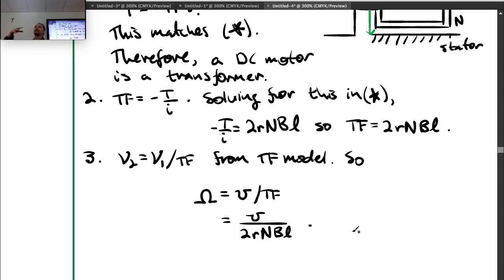Maybe you're trying to lift something using a motor and you can't lift it. You're just trying as much as you can. If you've got constant power, then as your omega goes down, your voltage goes down. If you're still delivering that power, you've got to increase your current more and more, and that's what happens. You start pulling more and more current.